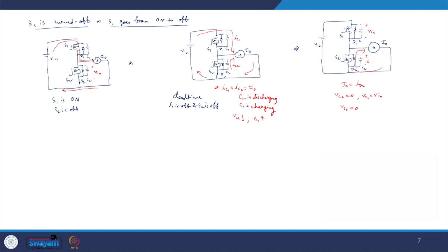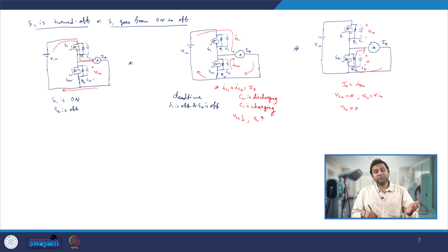Now we have understood that during the turn on case, if we somehow make the voltage go to 0 before the current starts rising through the device, we will get 0 voltage switching. So here we have made our voltage go to 0, and now when we give a pulse to the S2 switch to form the channel, the device will achieve 0 voltage switching, which will have negligible loss, or you can say 0 loss, due to the overlapping of voltage falling and current rising.